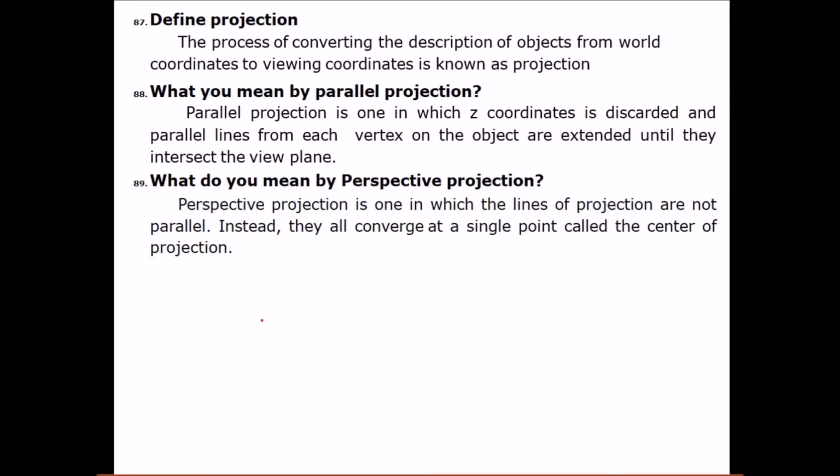So what do you mean by perspective projection? Perspective projection is one in which the lines of the projection are not parallel. Instead, they all converge at a single point called the center of projection.